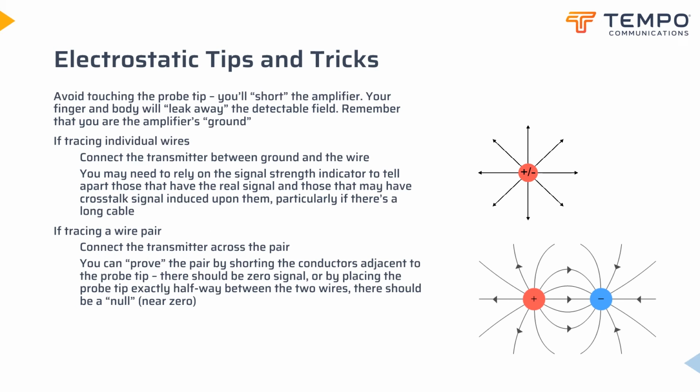Keep your mind thinking about the electric field when tracing wires. The conductor ducts the electric field to where it's wanted. Intervening soil, actual ground, or grounded metal can ground or shield that field. As the field surrounds the conductors, it can couple to other nearby ungrounded conductors. We call this crosstalk. It's one of the reasons we use twisted pairs, as the field applied across one pair averages out to a net zero when looking at adjacent pairs.